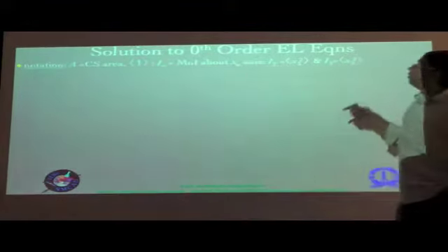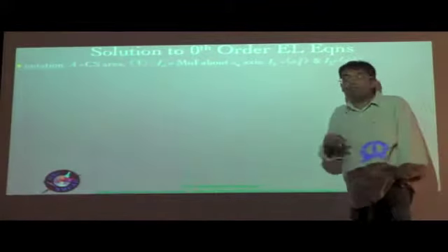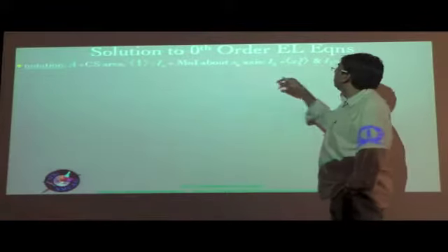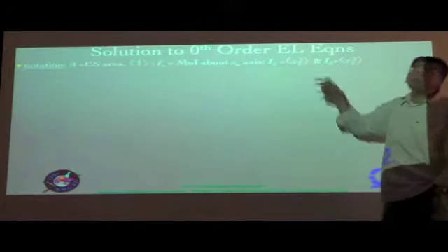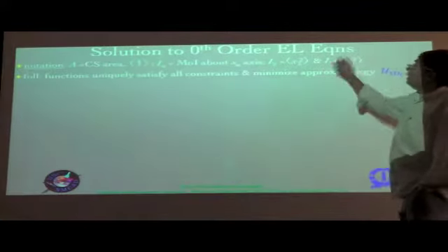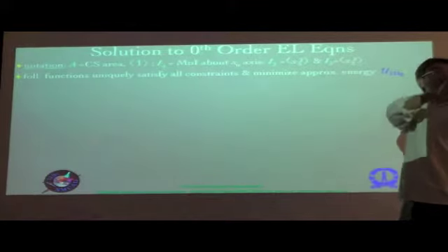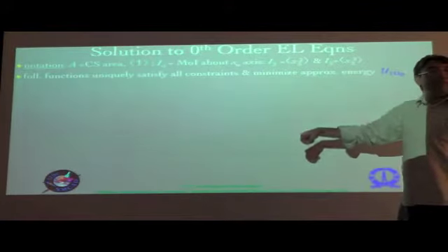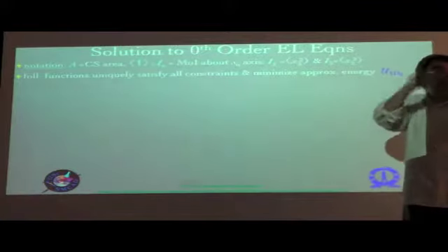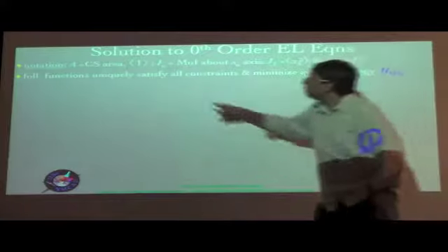And then I alpha would be the moments of inertia about the two axes x2 and x3, the cross-sectional axes, the coordinates that we have. So I2 would be integration of x3 squared, whereas I3 would be integration of x2 squared, both over the cross-sectional area. Now again, see, in these cases root g is not involved because x2 and x3 are not curvilinear coordinates. It's only x1 which is a curvilinear coordinate, and therefore that root g comes in only in a volume integral, not in the cross-sectional area integral. So that's another thing to be remembered.